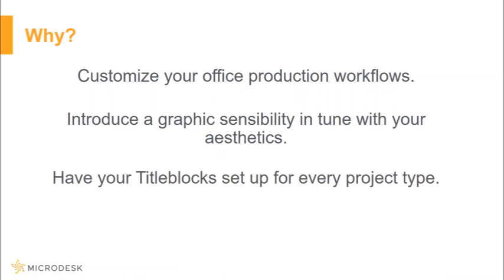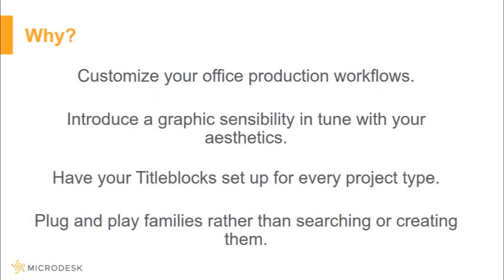You can definitely set up your title blocks for every project. A lot of time in terms of different title blocks you'd be setting up for anyone that's working CAD. This helps out, and they're all built into the template, so you can mix and match what title blocks you want to drop in and what parameters you want to include in those title blocks.